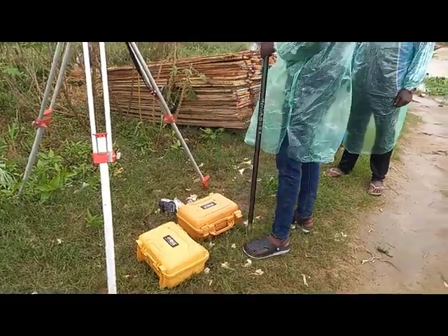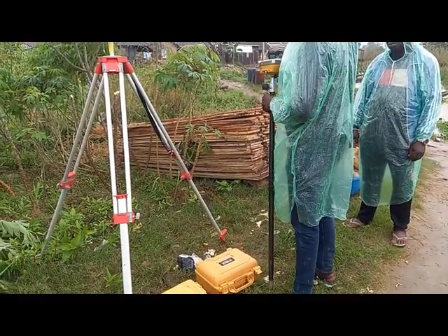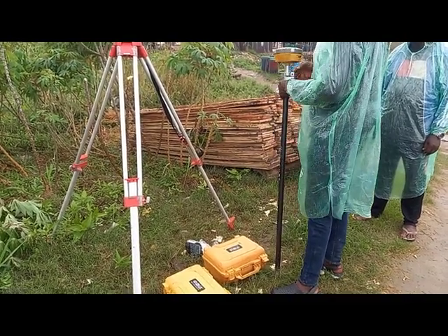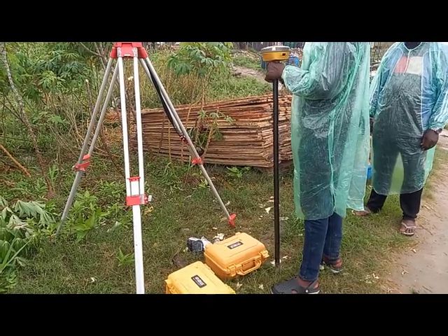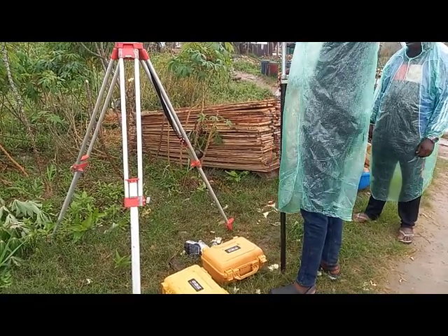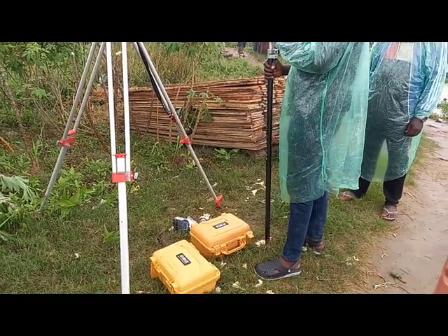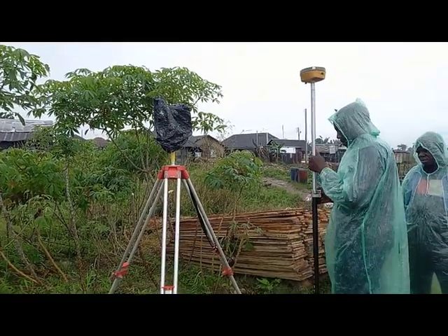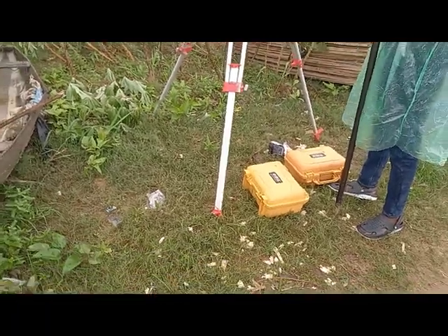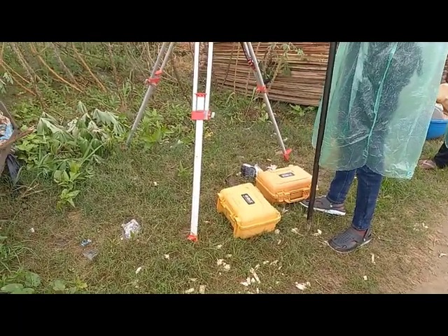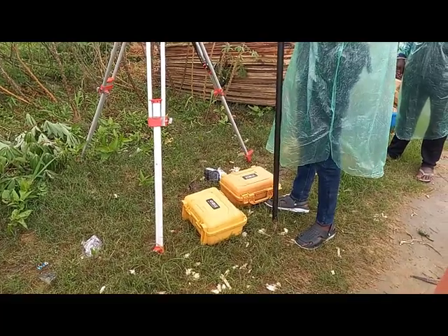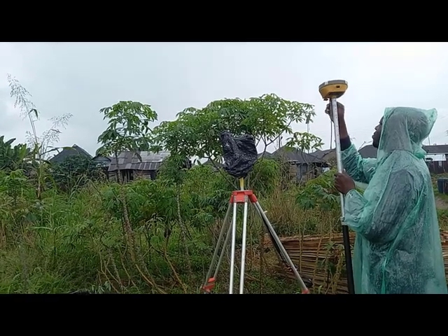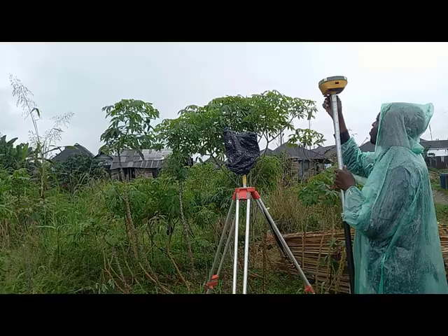So here you see him installing the GNSS rover. This is the particular GPS that is going to be taken around the site, the subject site for which you want to take topographic data for the survey. This is the GPS device that is going to be taken around the site in order to pick up data in terms of coordinates and elevation. It also has an antenna and battery as well. It's similar to the GNSS base, however, its function is different.